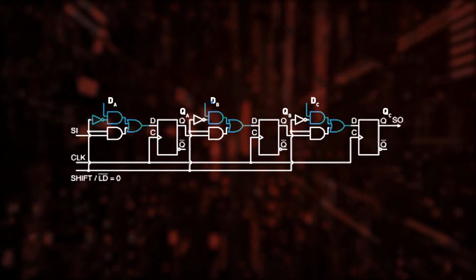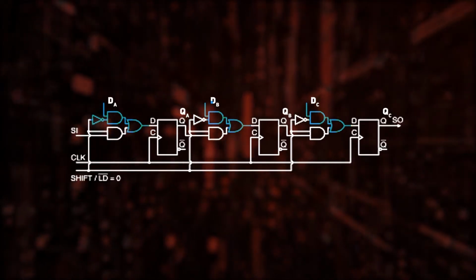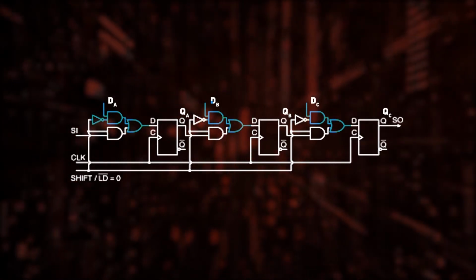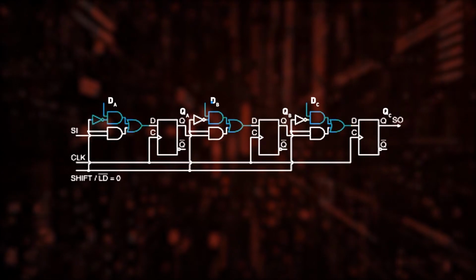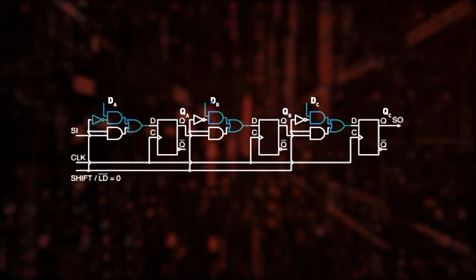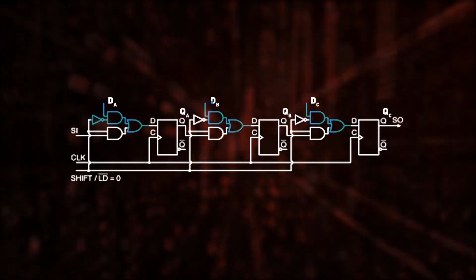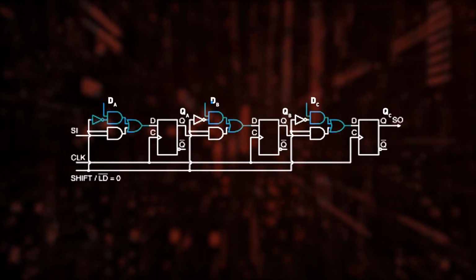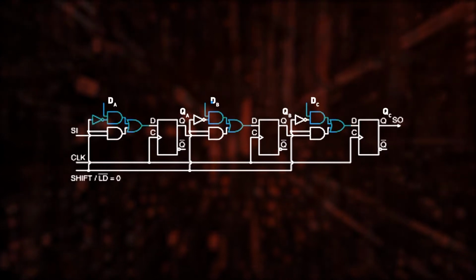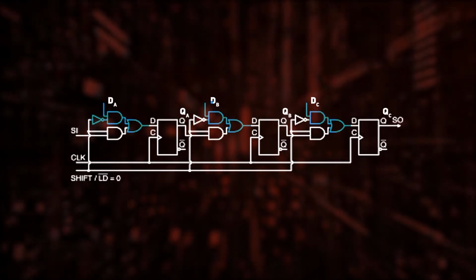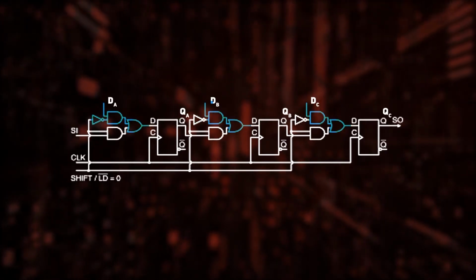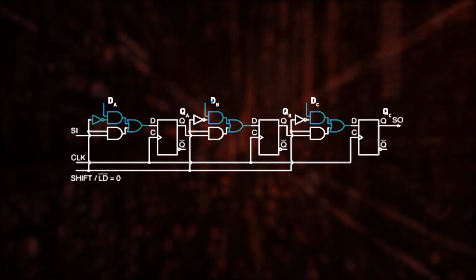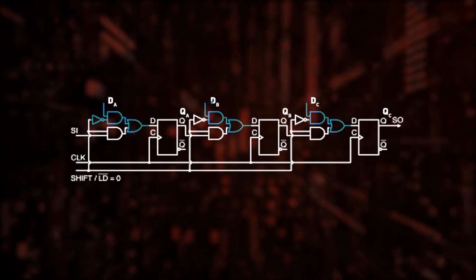For a PISO register, the data has to be loaded in parallel and the data needs to be shifted serially towards the output pin. You know that the parallel mode of operation happens in a single clock pulse no matter how big your data word is. So, in order to load this 3-bit data in parallel, you need to have 3 external inputs which you can see in the diagram mentioned as DA to DC.